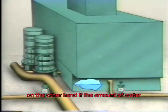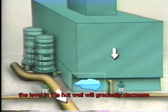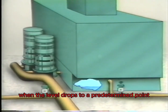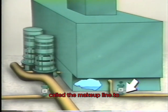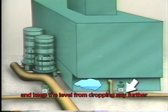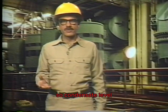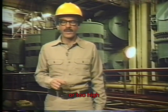On the other hand, if the amount of water entering the hot well is less than the demand, the level in the hot well will gradually decrease. When the level drops to a predetermined point, a valve starts to open in this pipe called the makeup line to allow water from other sources to flow into the hot well and keep the level from dropping any further. So, condensate level in the hot well has to be kept from getting too low or too high.